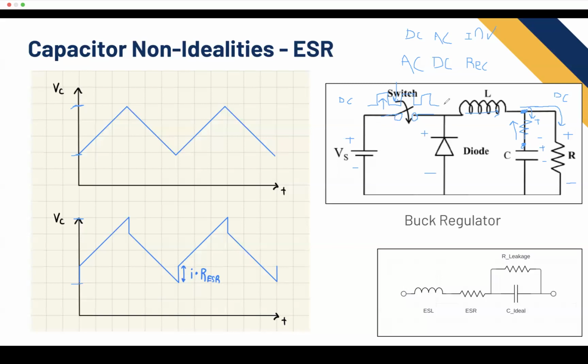So the voltage at this node is actually, it's like your inductor is going to be pulling current, right? So the voltage at this node just drops rapidly, and then it'll actually be lower than ground, and then the diode will turn on, and then basically it'll be ground.